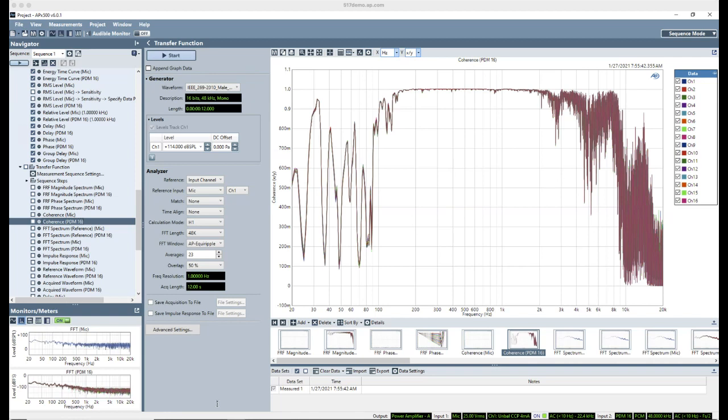Okay, another person asked, would like to do an amplitude step measurement and measure the noise in the presence of signal. How to realize that? The first thing I'll say about that is there's a very, very practical challenge anytime we want to measure noise out of a microphone capsule, which is you're going to need a test environment that has less noise than that, and that might be a test box inside of a test chamber.